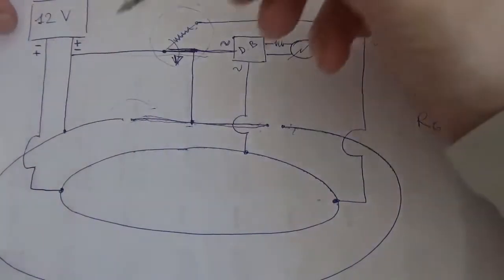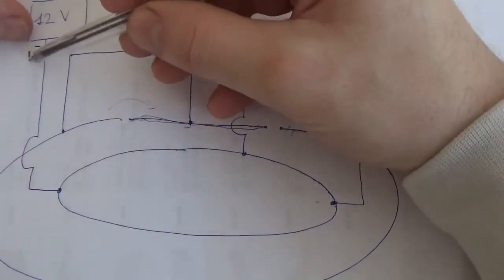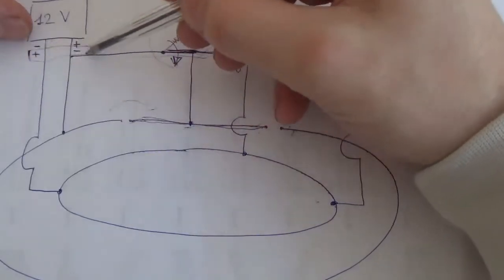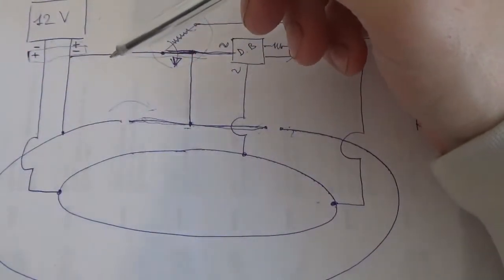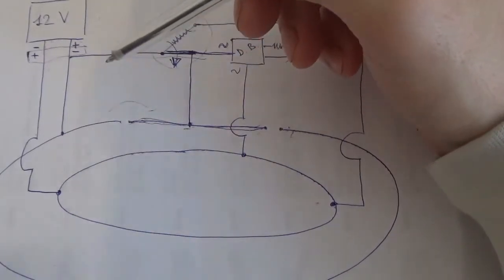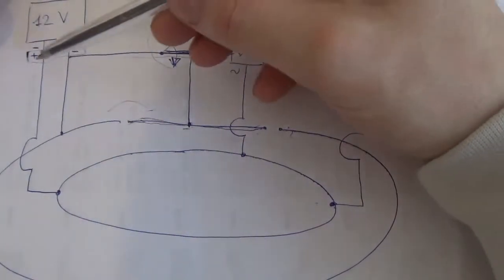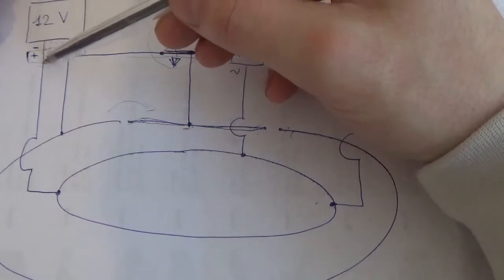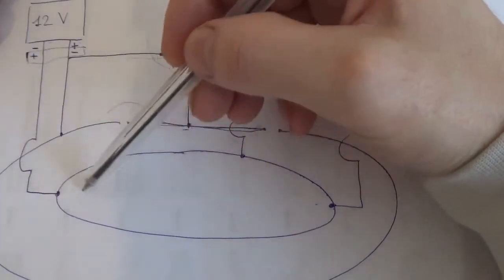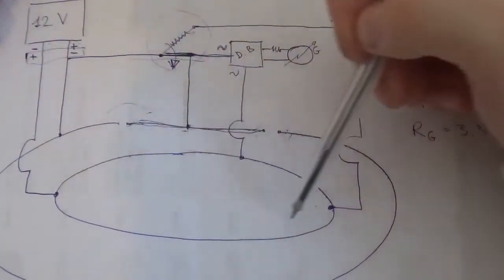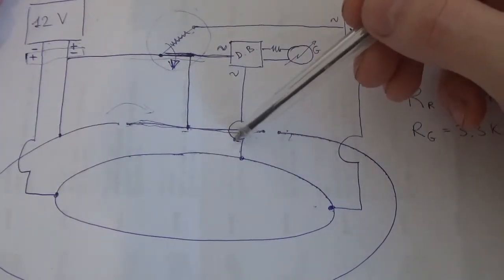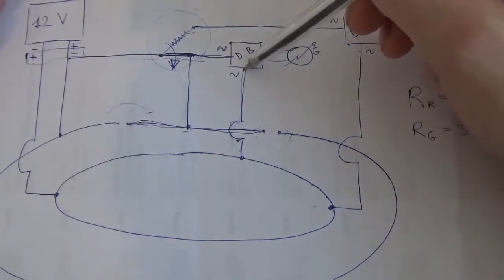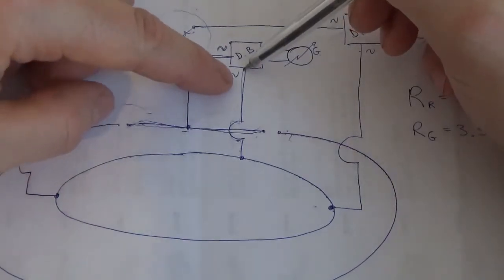Okay, let's do the same consideration in this second scenario, where the polarity is changing. Let's see if everything behaves as expected once again. The electric current is going to make its way in this direction. It's going to power up this side of the rails, and it's going to make its way over here through the diode bridge from the other input.